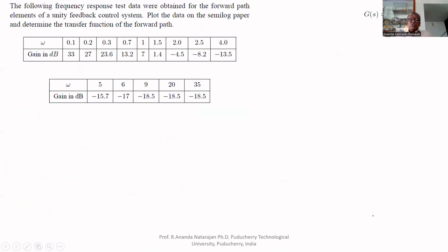Suppose you are given an instrument, it may be an amplifier or some other instrument. For that, you are required to find the transfer function by an experimental way. How can we find it? We have to find the frequency response for this. This is the magnitude response.